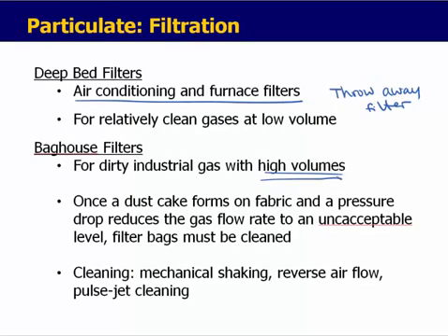Once a dust cake forms on the fabric and a pressure drop reduces the gas flow rate to an unacceptable level, filter bags must be cleaned. Cleaning can either be performed mechanically, by reversing the airflow, or by doing a pulse jet cleaning.